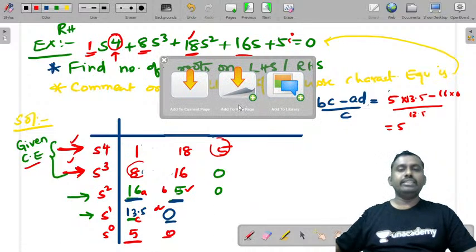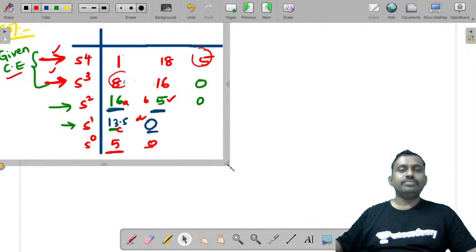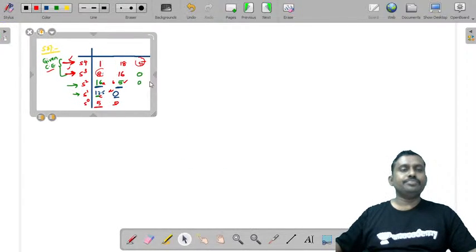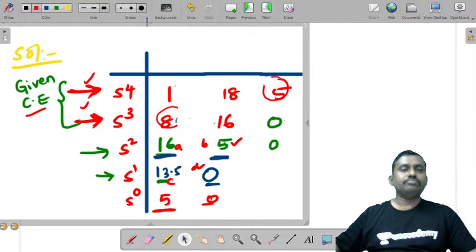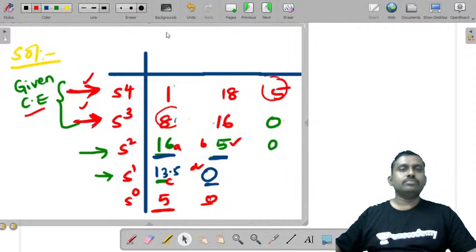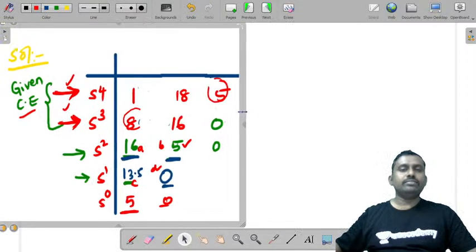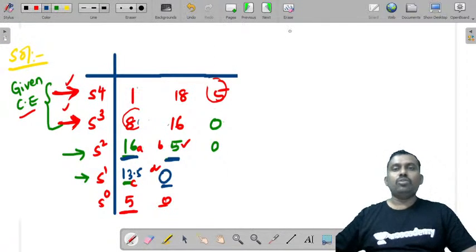Hope this filling of the Routh array is clear. So this we have done now. So this is the Routh array. Now, you only have to look at the first column element signs to comment on stability.